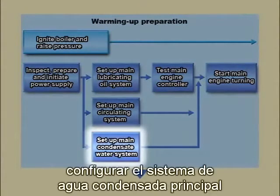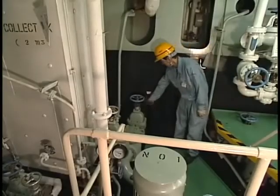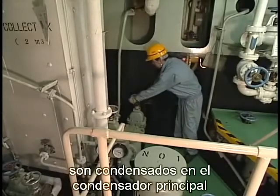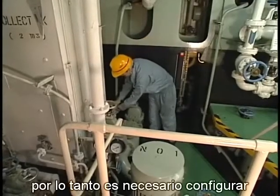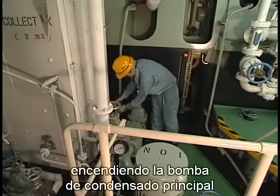Set up main condensate water system. As warming up begins, warming up steam and gland steam are condensed in the main condenser and the hot well level rises. Therefore, it's necessary to set up the main condensate water system in advance by starting the main condensate pump.